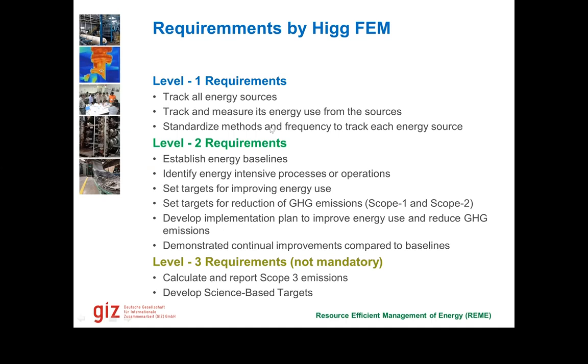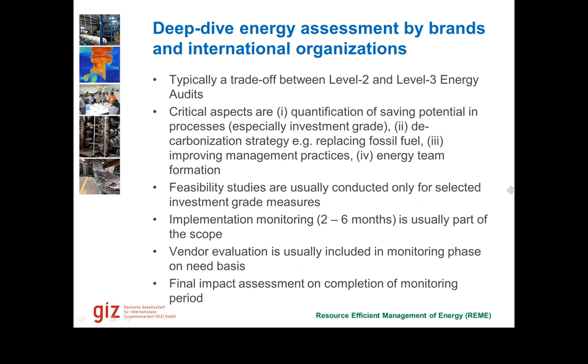Then talking about the deep dive assessments, many of you have already done that. I will try to summarize it here, that typically the deep dive energy assessments by brands and international organizations like IFC or others, Clean by Design, Apparel Impact Institute, these are typically somewhere between level 2 and level 3 energy audits. They are not typically only level 2 or only level 3 audits, because they have their own priorities. And so the critical aspect here is quantification of energy saving potentials, especially in the processes, not only in the utilities, but also in the processes.